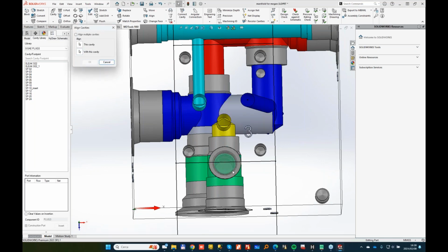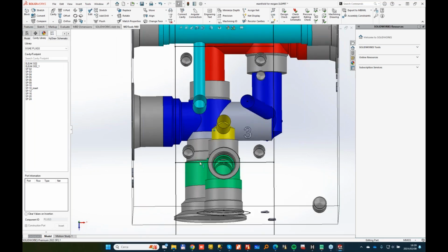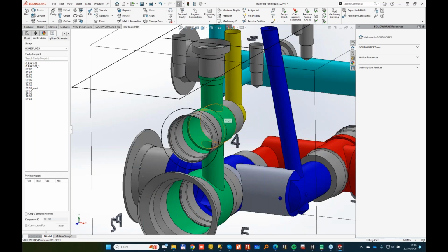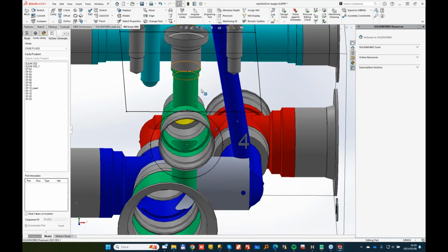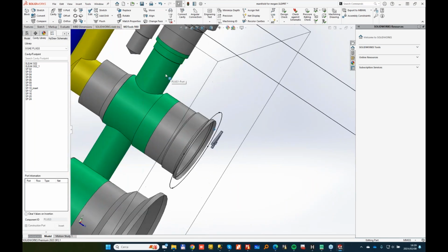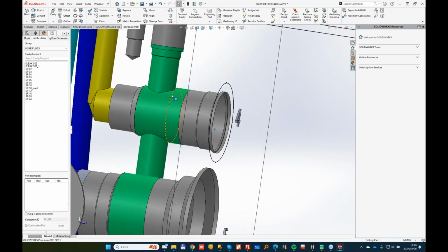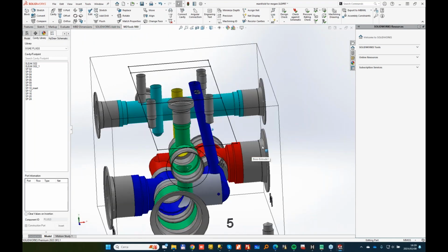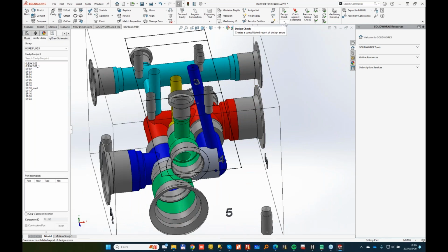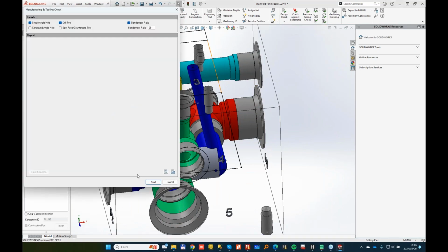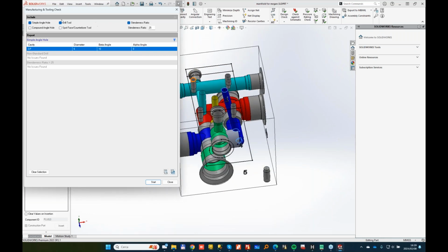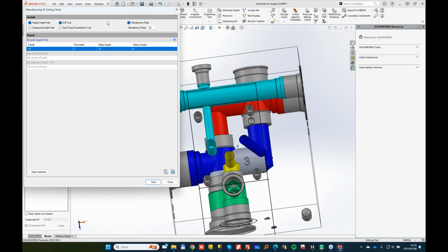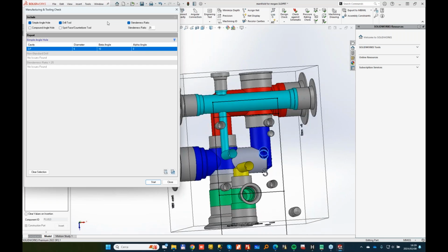The reason to do the alignment here and not with the bottom cavity is because this drill will go through the first cavity and then enter in the other. So to make better operation, it's better to go center to center, and then I do the offset connection just at the end. It will be possible to do a manufacturing check, which will show if there are inclined drills, but nothing else. So all the other manufacturing checks are correct. I just need to be aware that there is an inclined drill.